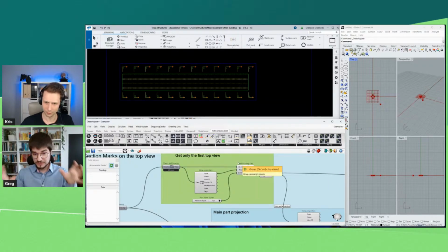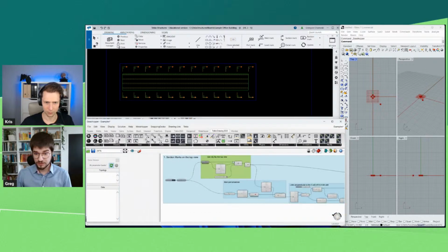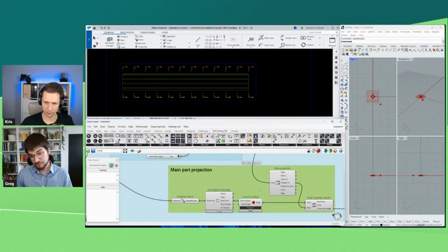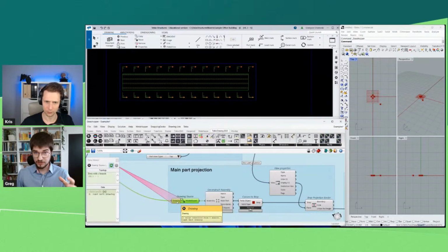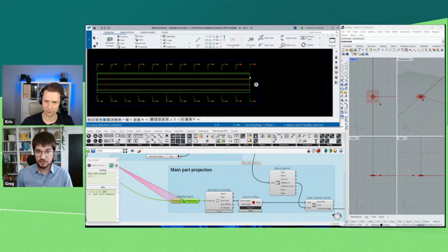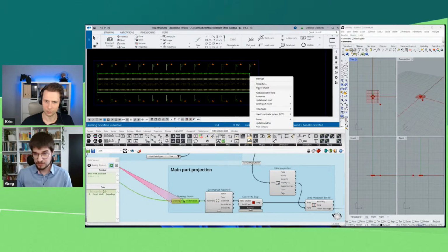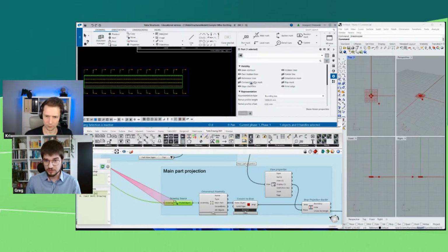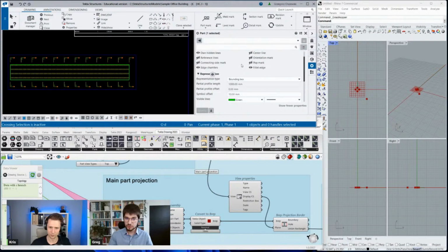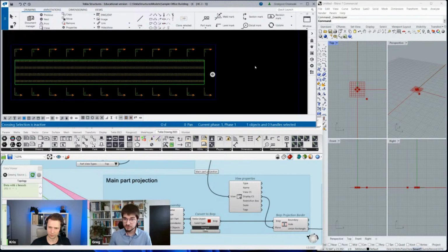So the purpose of this first block is just to get this view, and then it's the most important thing, I would say, that we started with the drawing itself, and this is the cast unit drawing. So we have to find out the model object to get the geometry, because you have to know that those drawing objects like this one, they don't have the direct geometry. So if I will find out the properties, I can change the properties of the visual representation. There's no connection to the model at that point. So I have to deeply under the hood go to the model.